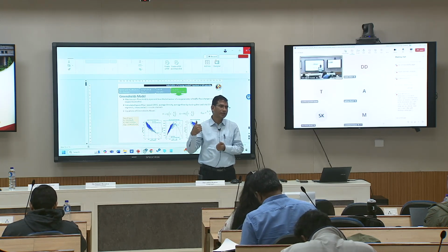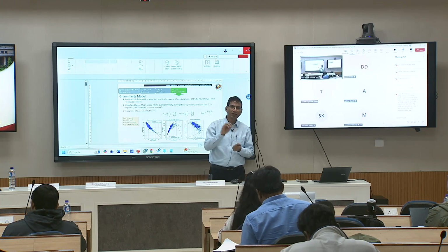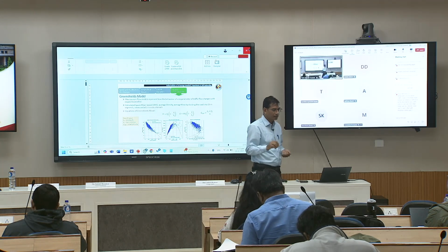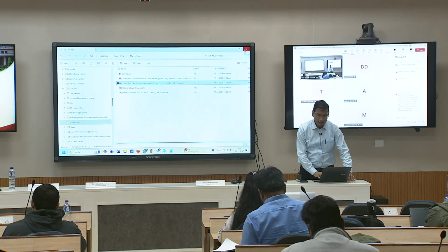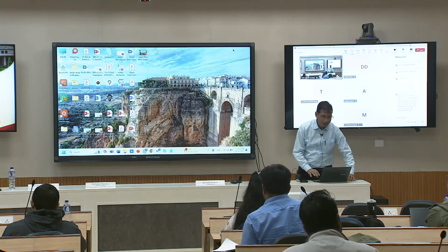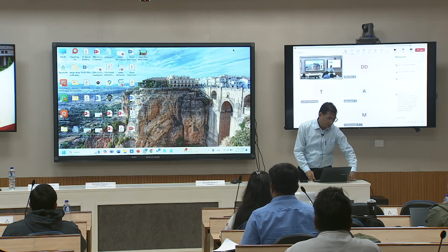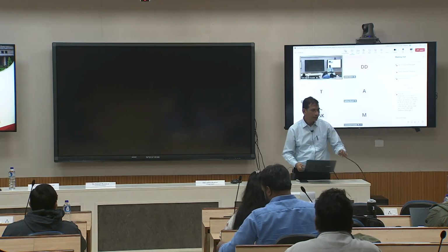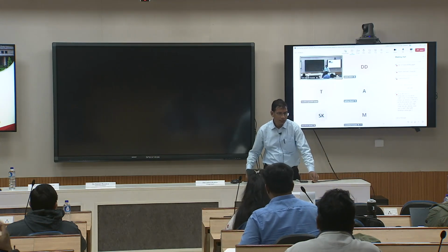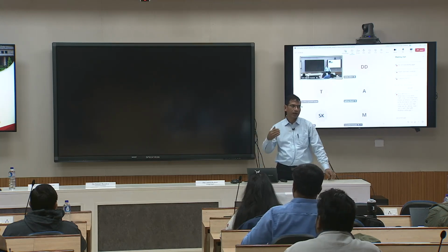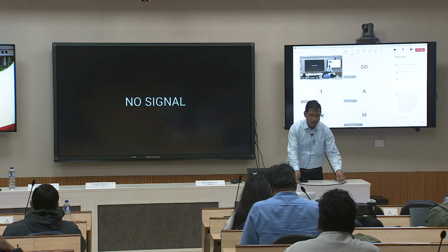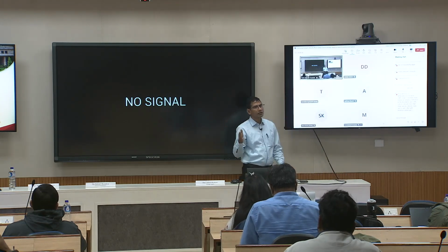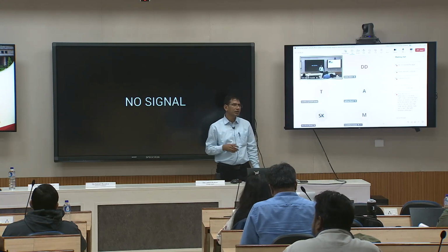If you have a number plate recognition system, that data can be mapped with it. Because if you have the number plate, you can know exactly what model of vehicle it is, and that gives additional information to ensure there is no misclassification in your data. Independently, a number plate recognition system alone can give you the flow value, how many vehicles have passed from a particular location and the type of vehicle, and then based on that you can apply PCU values. So flow you can get, but speed and such you will not get from that instrument.